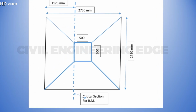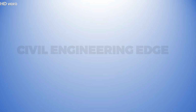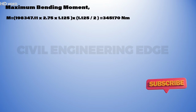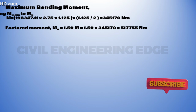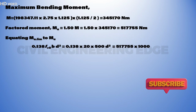Depth from punching shear consideration. Punching load = column load − reaction on column area = 1,500,000 − 198,347.11 × 0.50² = 1,450,413 Newton. Factored punching load = 1.50 × 1,450,413 = 2,175,619.50 Newton. Design punching shear stress for M20 concrete = 1.80 Newton per square millimeter.